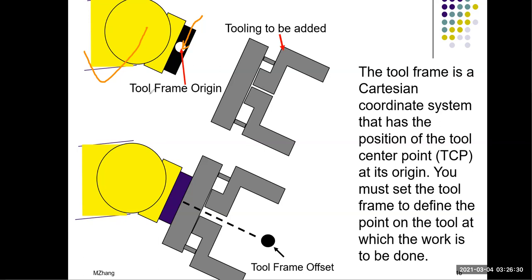They set the tool frame starting point at the center of J6, the end of the robot arm. That's the default, the best they can do because they don't know what kind of tooling you're going to attach to the robot. Then it's your job. Say you have a gripper and you decide to use this robot to grab parts. When you install the gripper on your robot, there are some extra things you need to do.